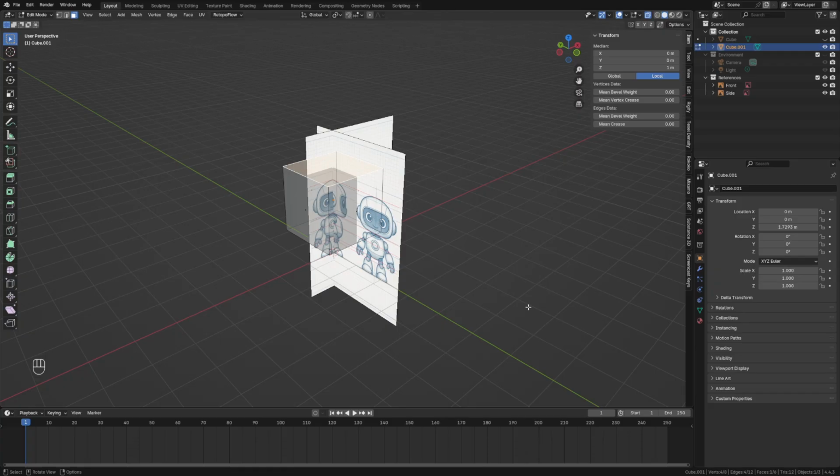And remember, all the shortcuts we talked about before work only when your mouse is inside the 3D viewport. That means your mouse must be here, not over there. On the left side of the 3D viewport, you have got the toolbar. It's where you will find tools like box select, move, rotate and scale. We are not going to use it much since we are relying on shortcuts. But if you ever forget one, just hover over a tool. It will show you the key. Right now the select box tool is active. If you click and drag, you will select everything inside that box.